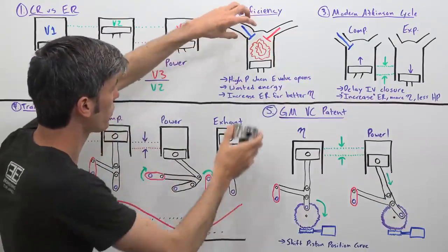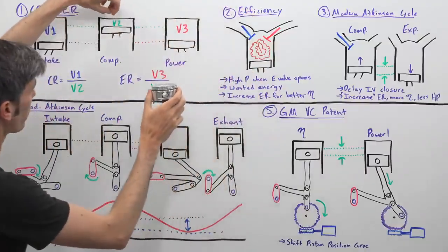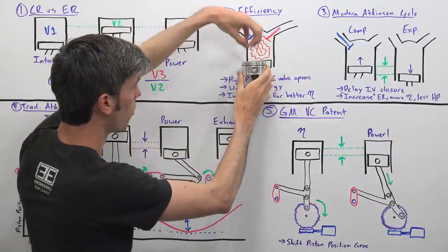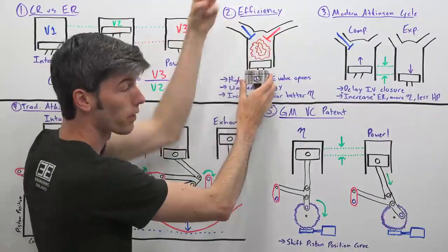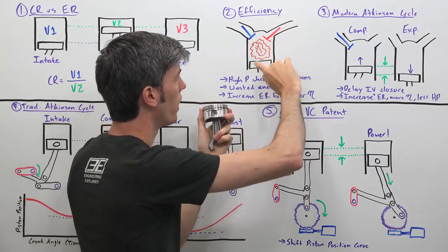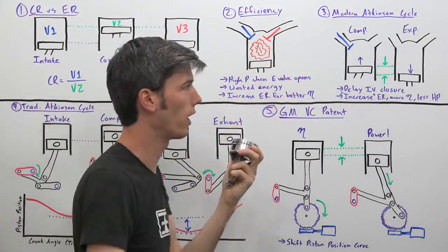If you look inside your cylinder, if you've just had that spark ignite, you have the power stroke occur, it pushes down this piston. Once this piston reaches the very bottom, there's still a very high amount of pressure within this cylinder. And then you open your exhaust valve and all that high pressure escapes out your exhaust.